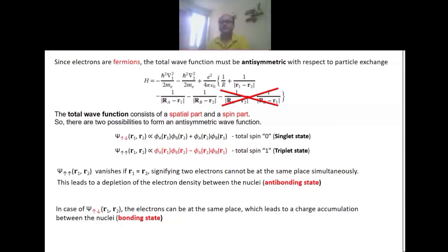Another set of semiconductors you can think of is gallium nitride, which he already mentioned in the previous lecture. Here you have seen that we have a set of elements: aluminium, gallium, indium. When they make compounds with phosphorus, nitrogen, even arsenic, antimony, they can create a compound semiconductor. That means two different elements are joining, making bonds to create different types of semiconductors. They are not elemental anymore.